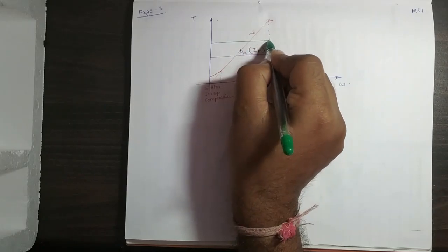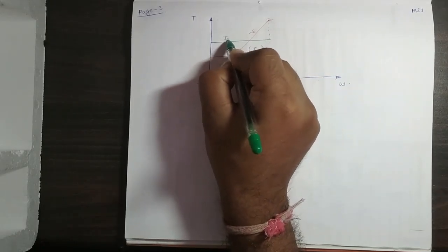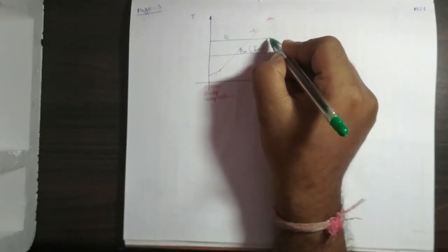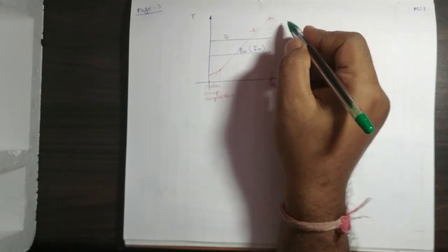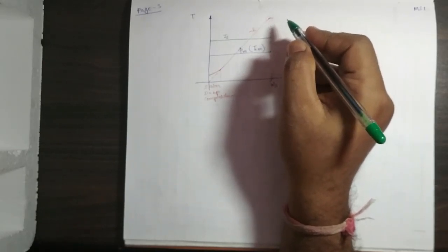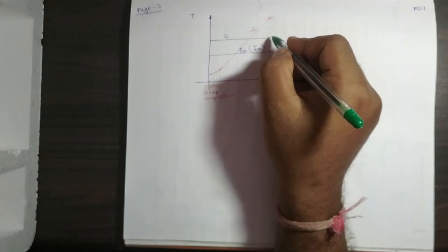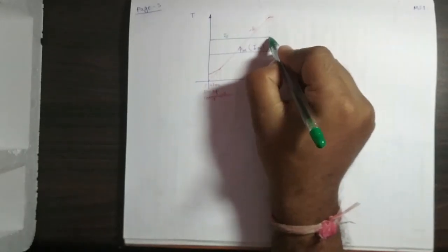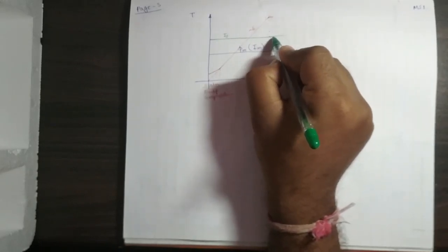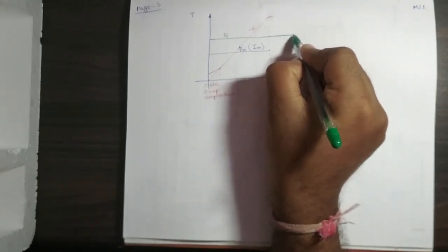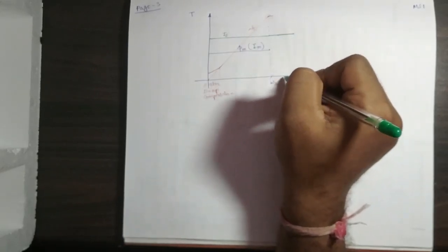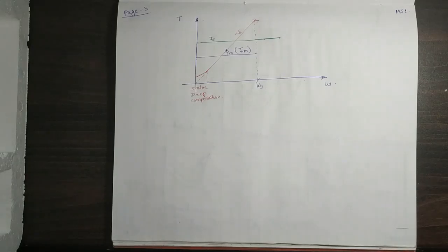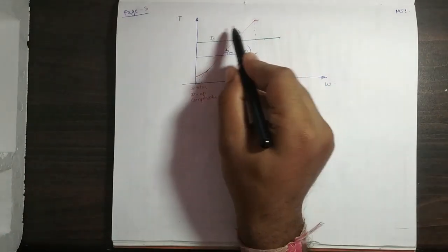Okay, and this stator current is taken as the rated stator current, applied throughout the motor, and this value also has some definite limit beyond which it cannot go. The same problem is there: while designing, the winding of the machine is designed in such a way that it can sustain only a certain amount of current. So suppose we are maintaining this current at some definite value above the synchronous speed, torque.